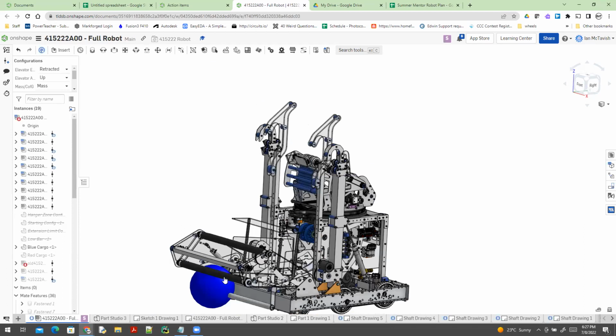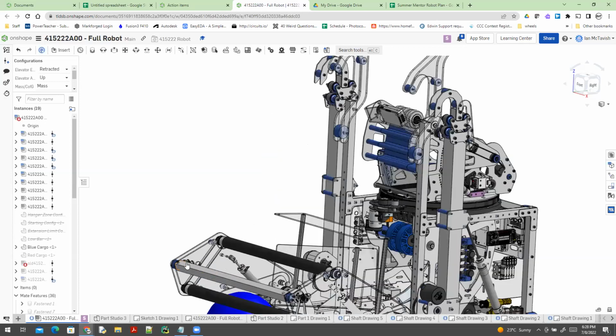There's our intake. So we have the bar at the front, we have the crash bar. After our North Bay competition, we realized that a 16th inch aluminum is not strong enough for that particular design. So if you're going to do that, you either make it really solid so that when you get nailed, it's not going to buckle, or you make it so that the intake will automatically fold out of the way.